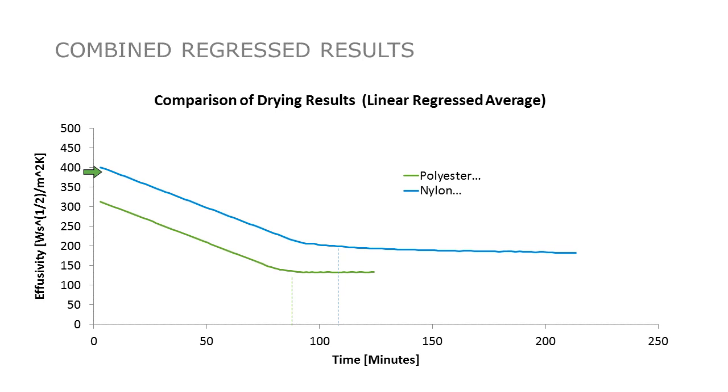So there's a few things that are interesting in looking at this. Eventually they settle out, when the material is dry again, and that's when you get kind of this steady state effusivity of about 200 versus 150 units. There's a significant increase when the material is wetted. So almost a doubling of the thermal effusivity. Actually more than doubling the thermal effusivity with not a lot of water added.